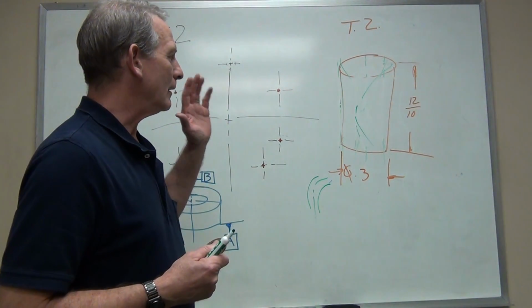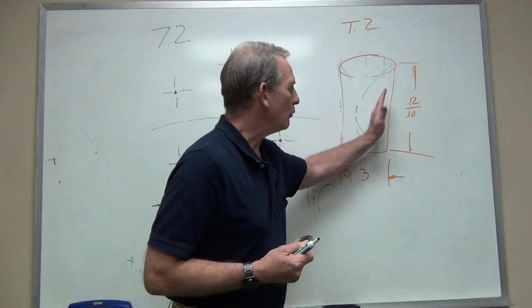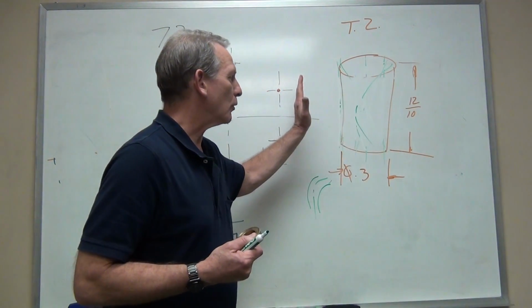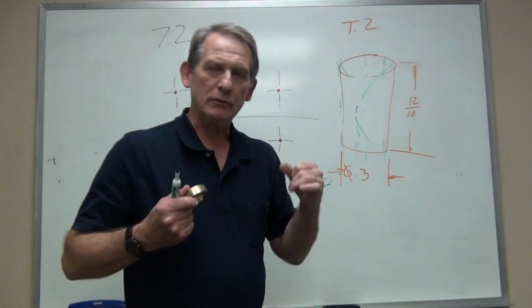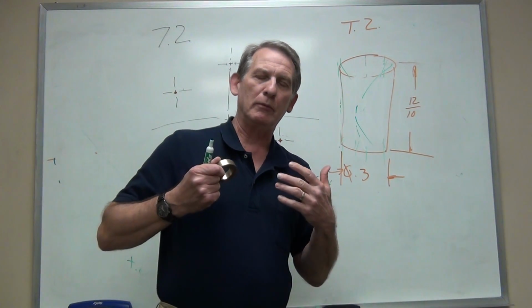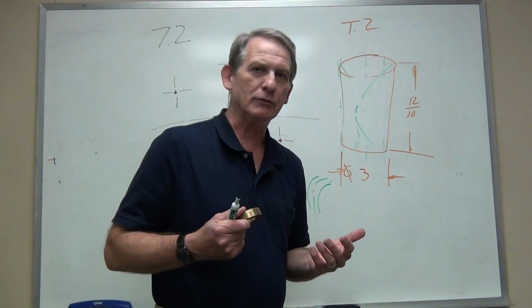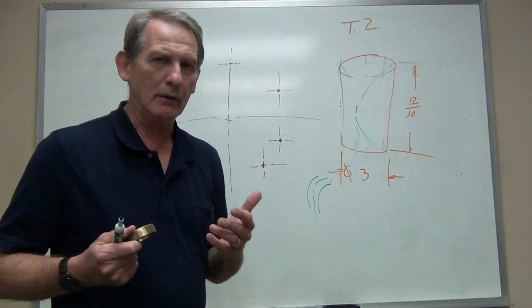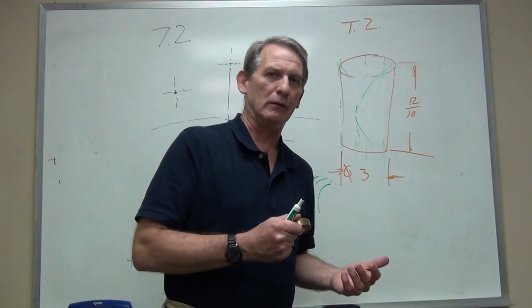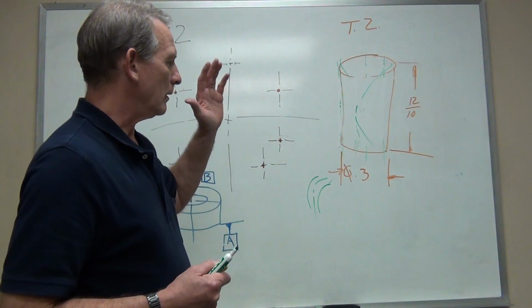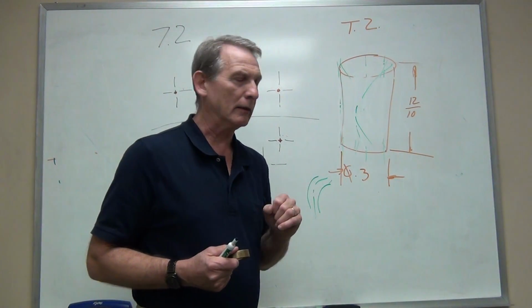So again, that's why we have the additional tools, is that we may want to control the translation to some size of tolerance, and we may be able to allow a larger tolerance for straightness or orientation. And if we want to do that, we have to create another feature control frame with another tolerance zone and take care of that specific aspect separately.